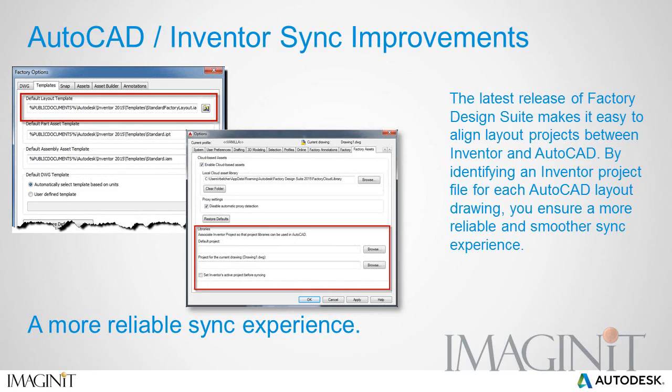The sync experience between AutoCAD and Inventor has been enhanced with the 2015 release. The latest release makes it easy to align a layout project between Inventor and AutoCAD. By identifying an Inventor project file for each AutoCAD layout drawing, you ensure a more reliable and smoother sync experience.